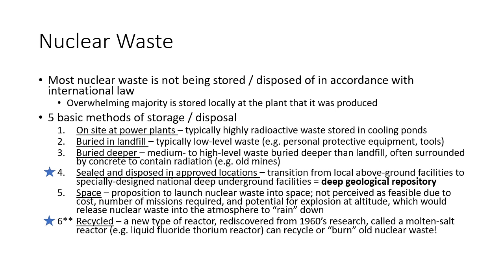You can bury this stuff in a landfill. So low-level waste like personal protective equipment, tools that you use can be sealed in steel drums. That drum can be lined with concrete and then just disposed of in a landfill. Typically, what you're going to do is have alternating layers of clay around this or even concrete around these things in your landfill so that they're never accessible.